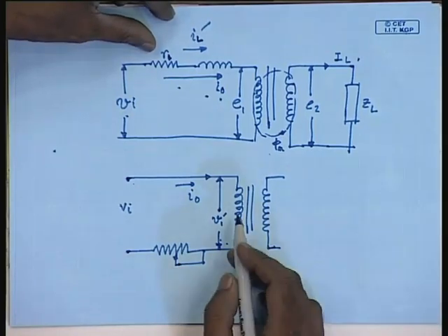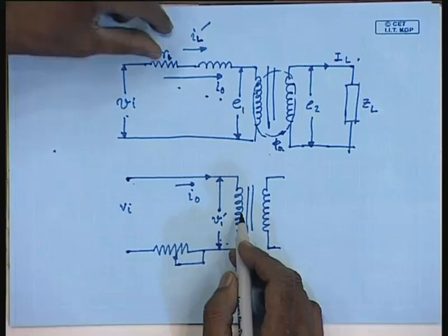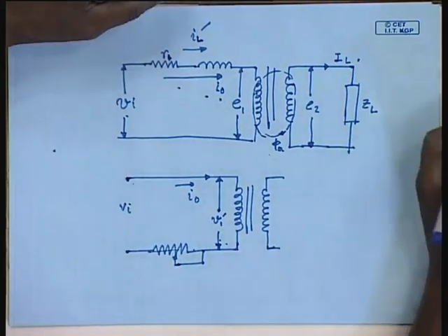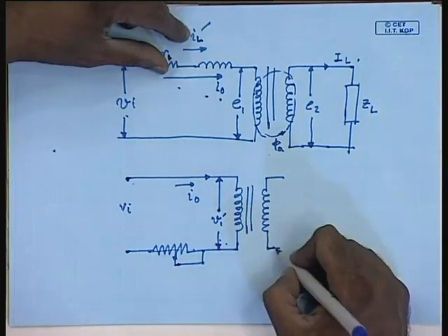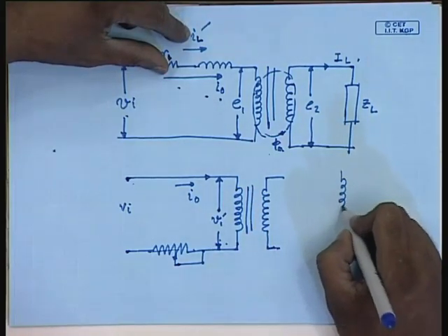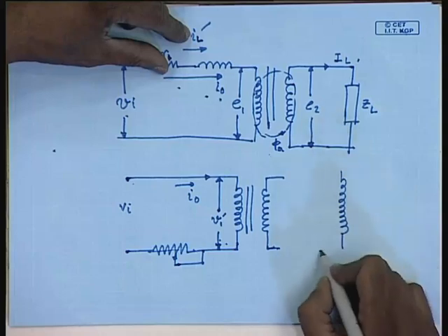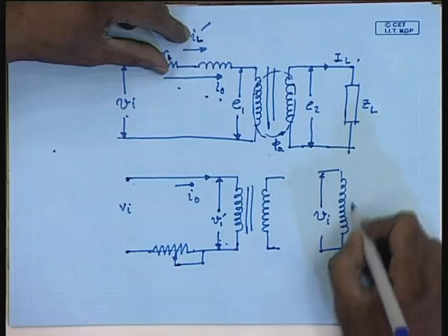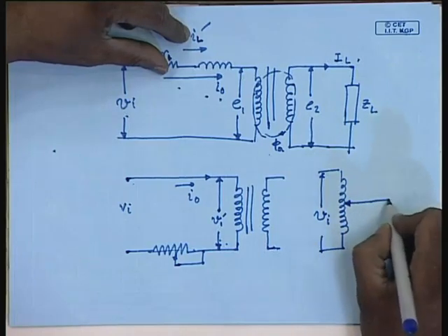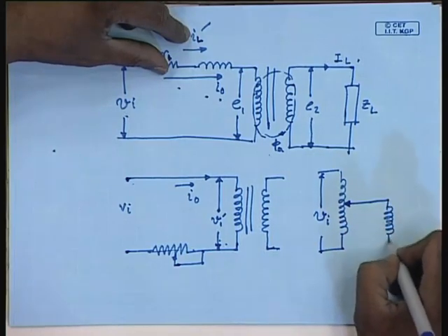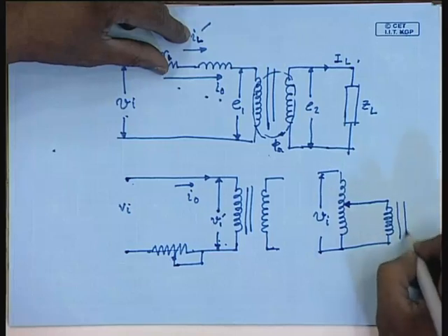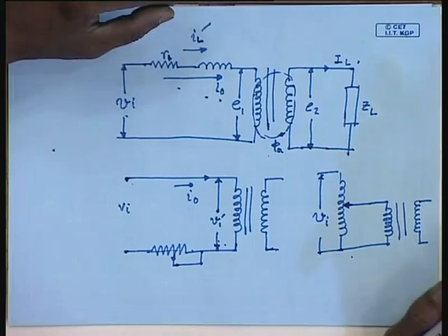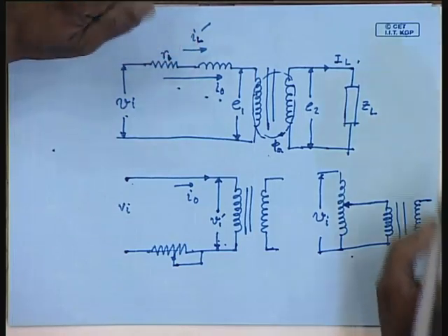Hence, for doing a no load test under such a situation, it will be preferable, instead of using a resistance to drop the voltage, to use an auto transformer, a variac, in order to reduce the voltage to the desired level, because the induced voltage in the auto transformer will be almost sinusoidal.